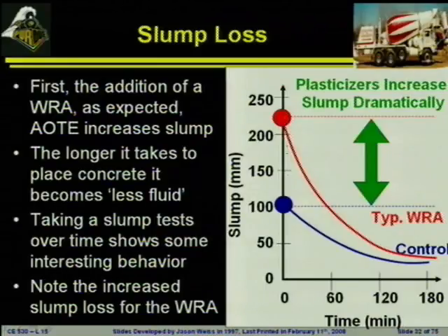So we've got a lot more of the system that's being workable, but by the time it sets, it's going to have the exact same slump. At setting time, the slump of our concrete is going to be 0. So it's got to get somehow from a 7-inch slump, a 5-inch slump, down to that value of 0. And one of the things that people get really worried about with using water reducers is the fact that these can change dramatically while the concrete is on site or while the concrete is being placed.